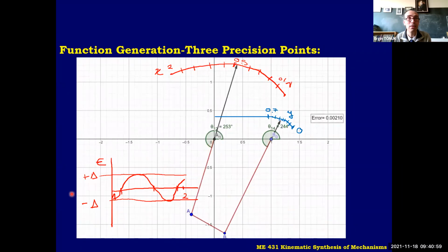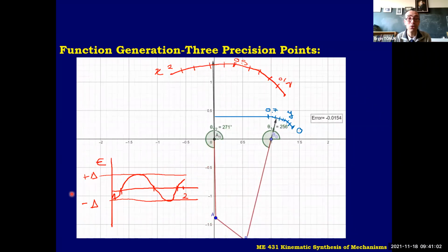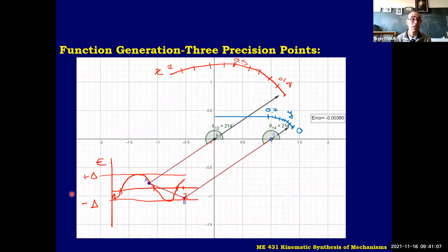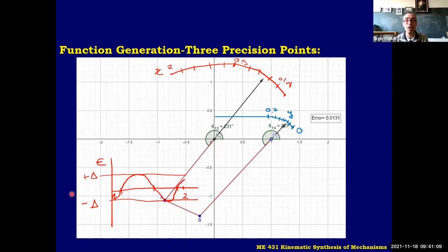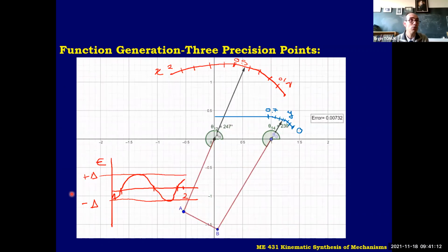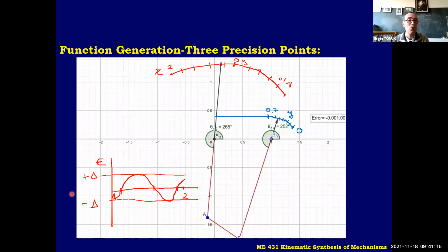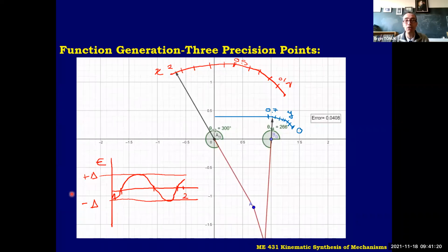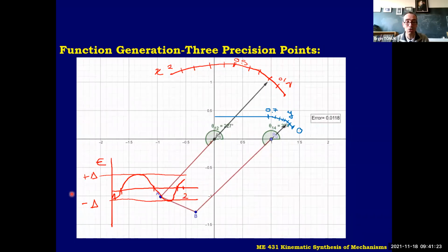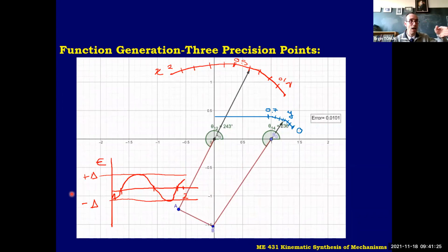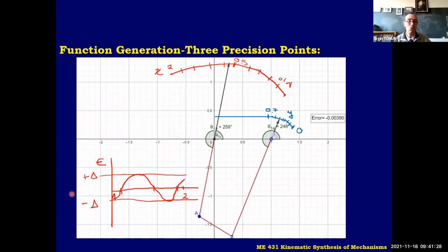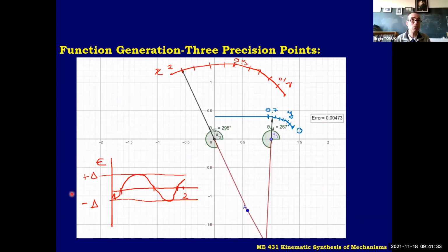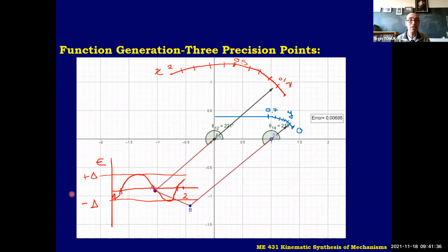Any questions? Any other questions? So as you see, we can't satisfy such a continuous function with linkage mechanisms because the number of design parameters is limited. However, for CAMs, at least theoretically, you can satisfy Y equals ln X or whatever the function is, as long as it's continuous, because the surface of a CAM is a continuous surface, okay? You can shape the surface as any analytic function or as any motion you like. That's the difference between CAMs and linkages, but